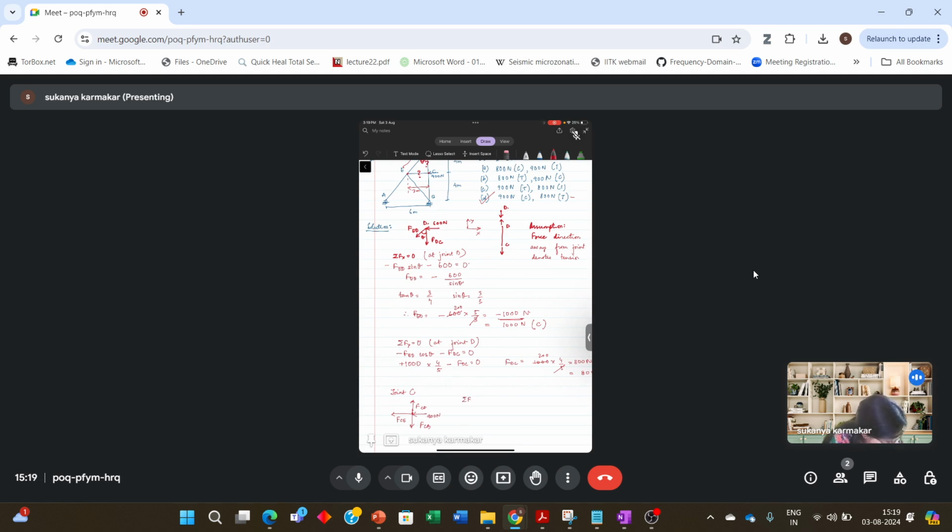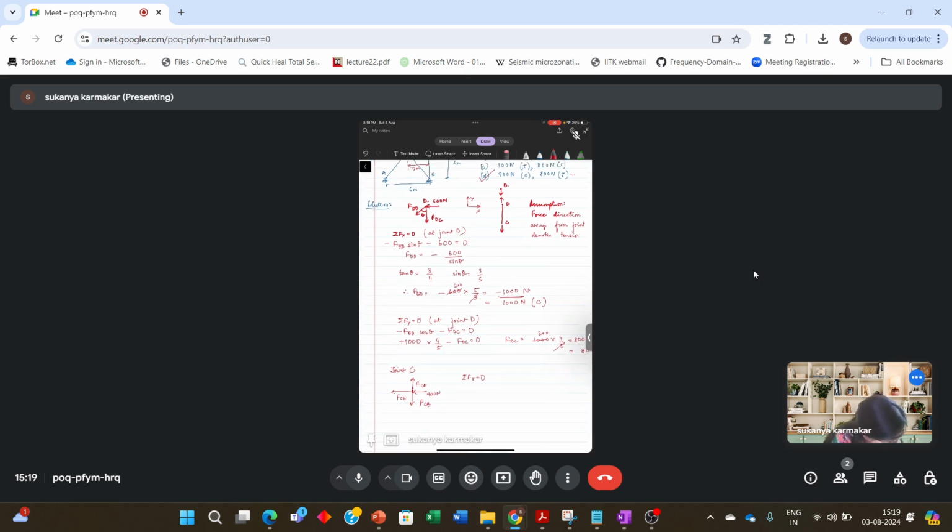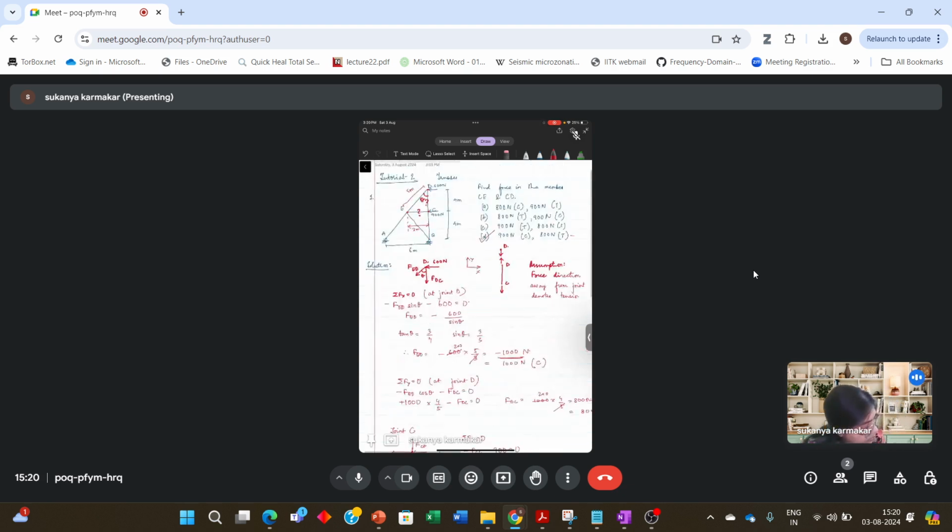So I will do summation of Fx is equal to 0. So minus FCE minus 900 is equal to 0. So FCE is minus 900 Newton, meaning it is 900 Newton and it is in compression. So this is the correct answer. Let's move on to the next question.